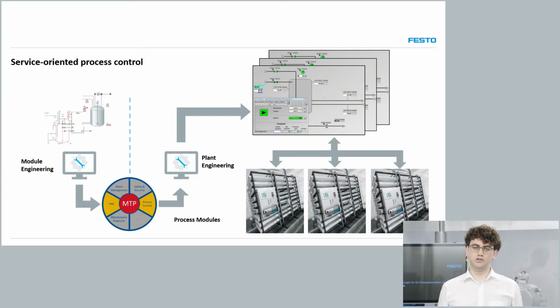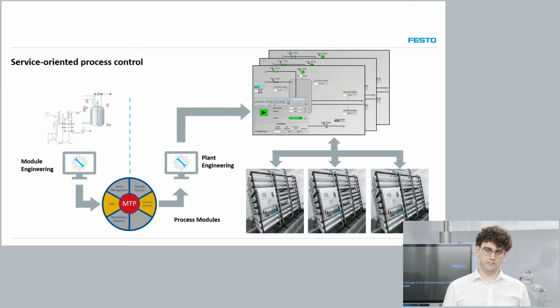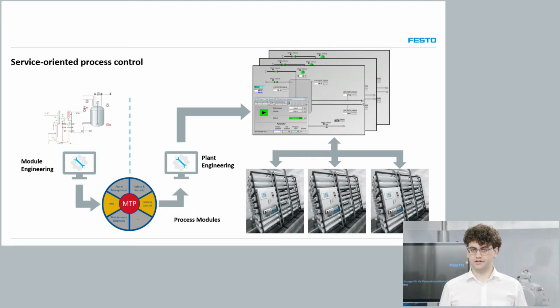So the module itself with the reactor is offering a reaction service that we can call from the process orchestration layer. We can start, stop, pause it, abort it, and the interfaces to do so are always the same, independently of the module and the module vendor. So here we see 3 different modules offering those services. The complexity of the skill, of the process functionality of the module, is encapsulated and therefore easy to work with.